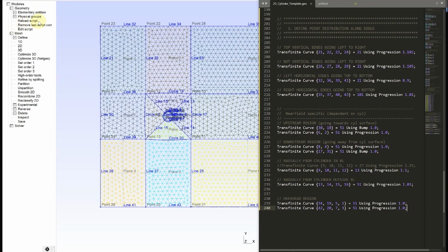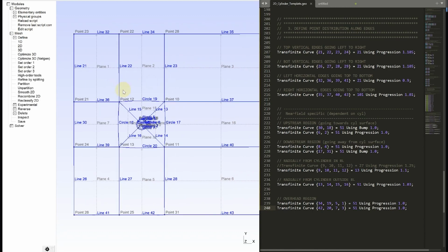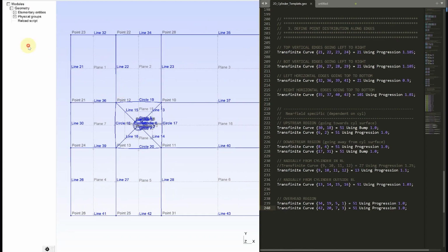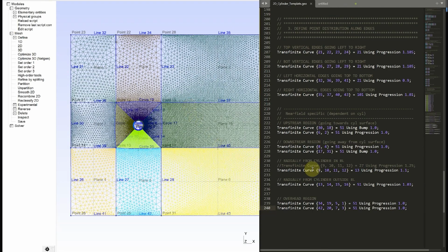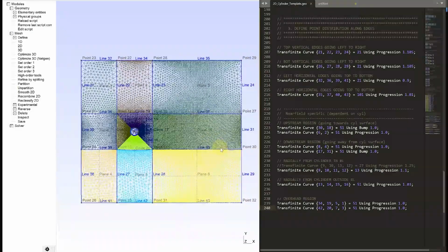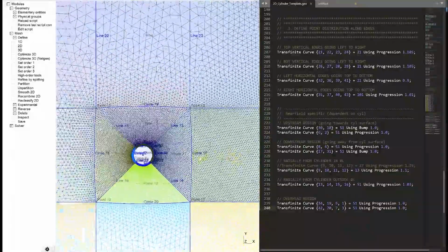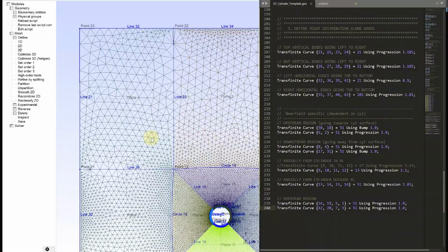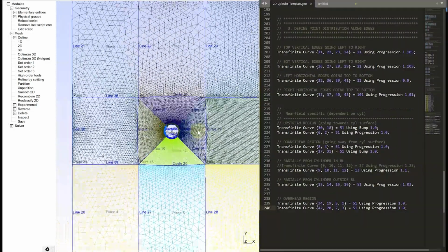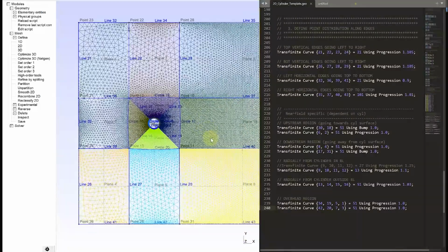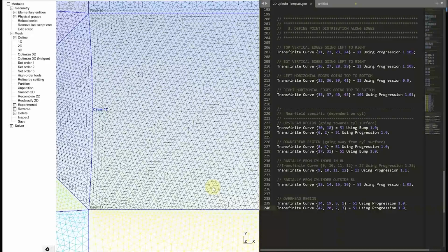Save it and reload script. Sequentially click on 1D and 2D. Now you can see you obtain a much finer grid, even though it still looks a little bit different from the mesh you've done in lab 1, because these cells are in the shape of triangles. And what we want in lab 2 is for you to generate structured mesh. So, in other words, the cells should be in the shape of quadrilaterals.